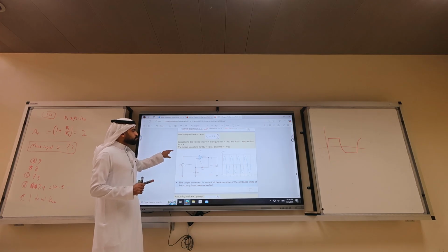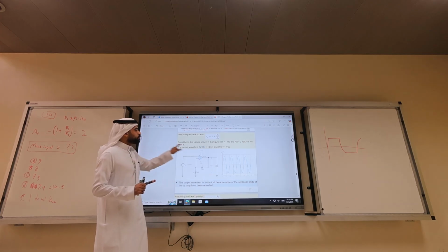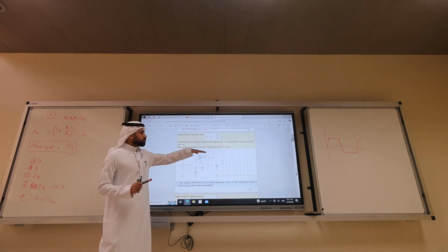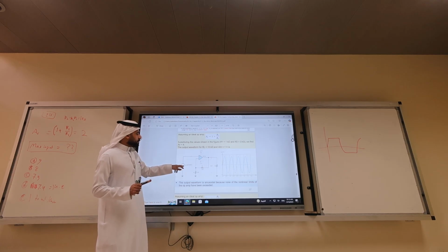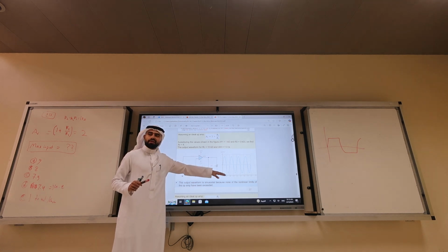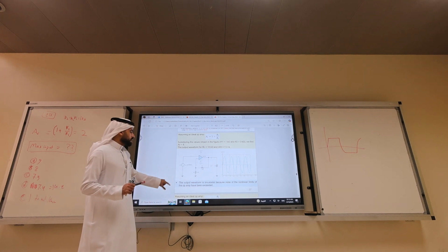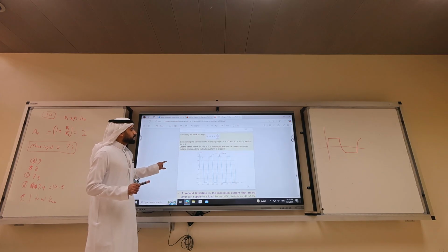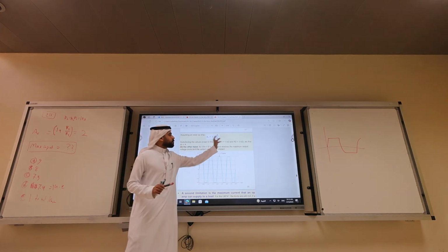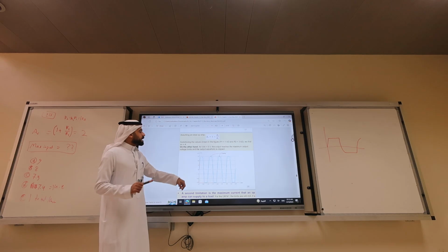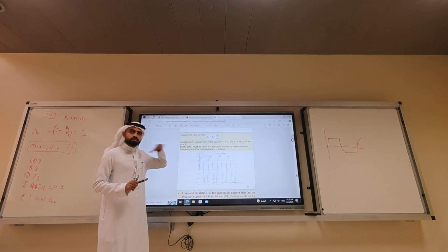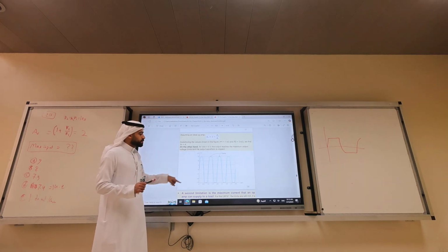Get it? So the output, if you have an input of 1, do you have clipping here? No, because the maximum is 1, so you get 1 and -1 times 4, you get 4 and -4, you're away from the clipping. Okay, that's a good example. When do you have clipping? For example, this is another example where we have a clipping, that's the 14. If you have the gain of 4, 4 times 5 is 20, you get clipping. So just make it below. It's a design problem. Don't make it exactly at the 15, make it just below. Okay?